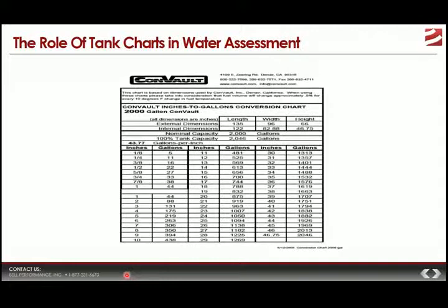Well, if the water volume is sizable enough, and in this case an inch is sizable enough, what he's probably going to want to do is call somebody, whether it's a fuel polisher or a tank service company, to come and mechanically remove that water, essentially pump it out. So they would pump out the water, and then they would use a water absorbing treatment, a chemical treatment, to mop up the remaining trace amounts of water from that tank.